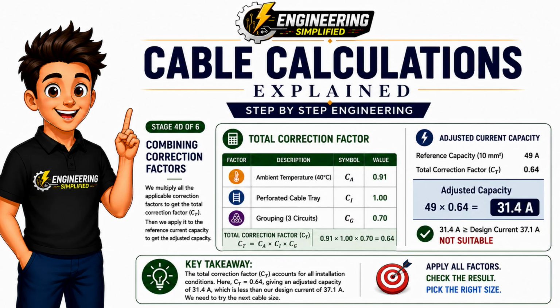Now we combine all of the correction factors. We multiply the ambient temperature factor of 0.91, the installation factor of 1.00, and the grouping factor of 0.70. This gives us a total correction factor of 0.64. We now apply this to the published current rating of our 10 square millimeter cable. The original current capacity was 49 amps. After applying the total correction factor, the adjusted current capacity becomes 31.4 amps. Our design current is 37.1 amps, so this cable is no longer suitable. This is an important lesson in cable sizing.